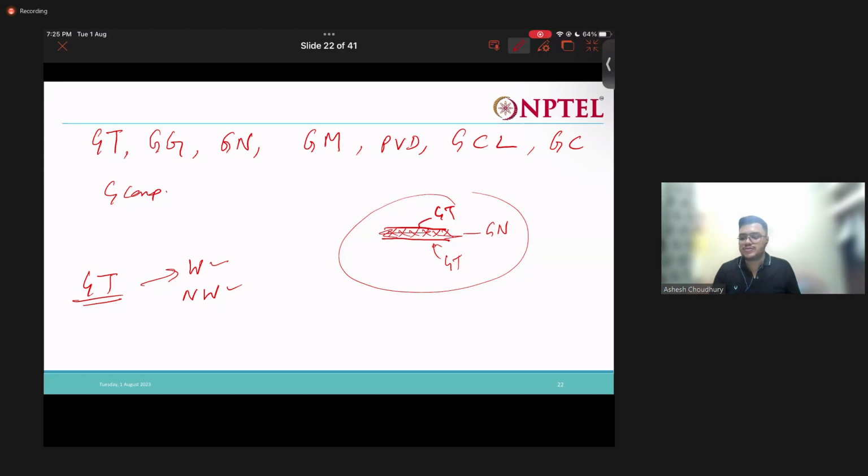Woven geotextile will be something like a knitting structure. The textile that we are wearing is also a textile, right? This clothing is actually woven. If you look closely, you can see there are some definite patterns in it. It's woven with a machine, properly woven, properly knitted. Similarly, we construct a geotextile. Geotextile is also a textile, but the purpose and the strength of these two are different, right?